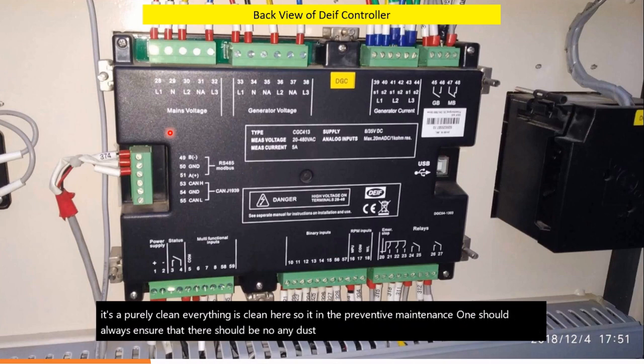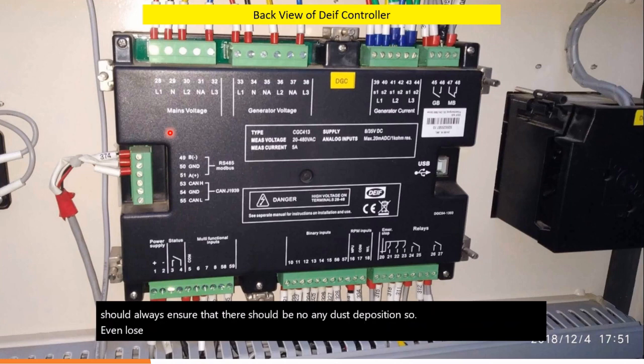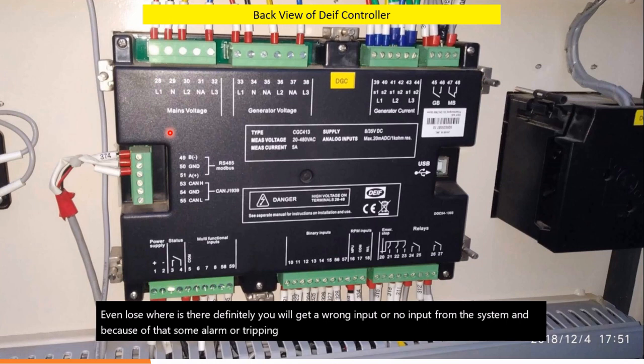If any loose wire is there, definitely you will get a wrong input or no input from the system, and because of that some alarm or tripping might come. So for the electrical side, basic tightness of all these connectors is mandatory.